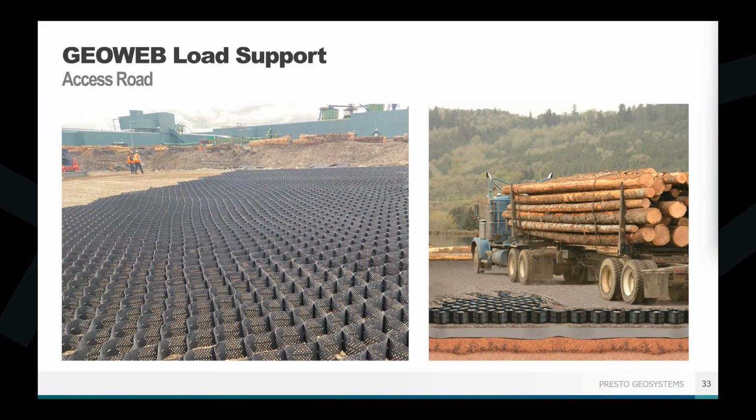This makes sure that you have that really good free drainage through the void spaces of the stone. So in this case, they did need an infill to be a little bit more engineered because they had a specific goal in mind, drainage. So that's something to sort of balance out. Maybe you have on-site material that you could use, but you don't exactly know the quality, you don't know the gradation. There's a lot of fines to it.